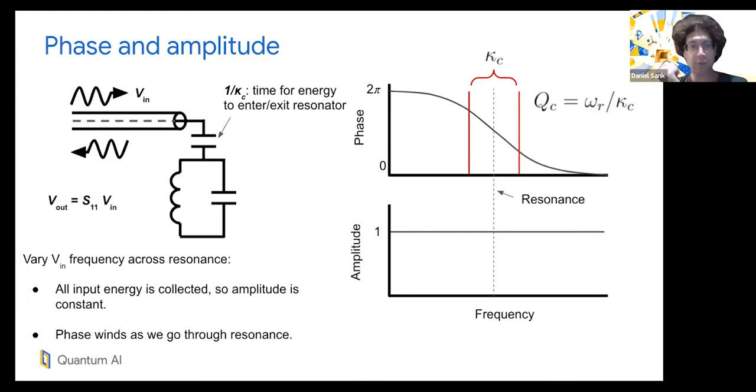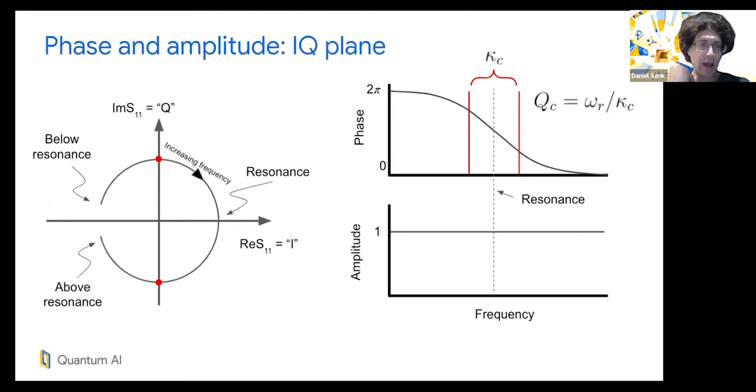Yeah, this is the basic principle of the measurement. And then Abe, next slide. Another useful way to plot this is on a two-dimensional axis. So here, what I'm plotting is the amplitude and phase of the reflected signal on a two-dimensional grid. So amplitude is distance from the origin and phase is the angle.